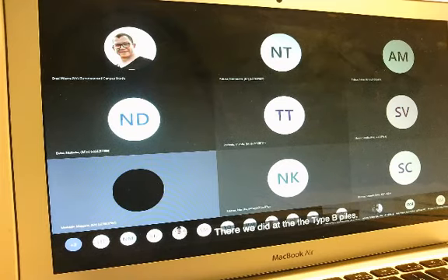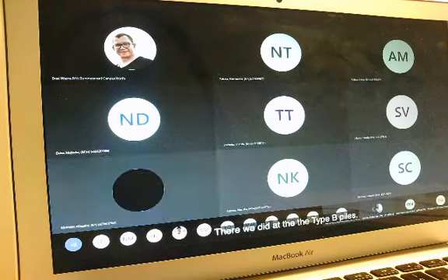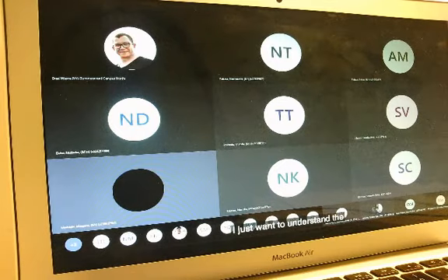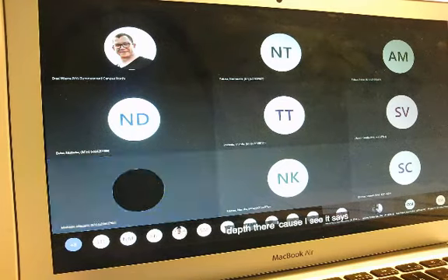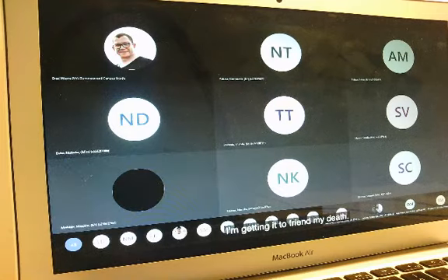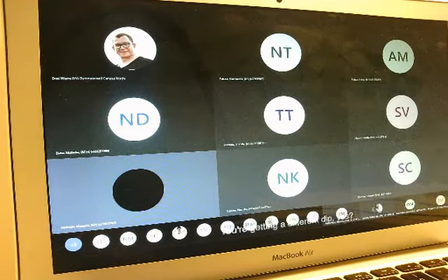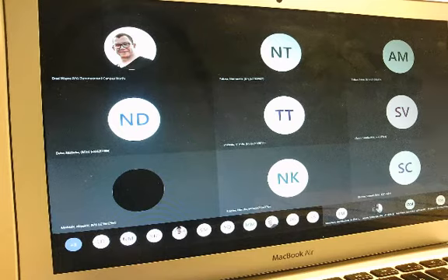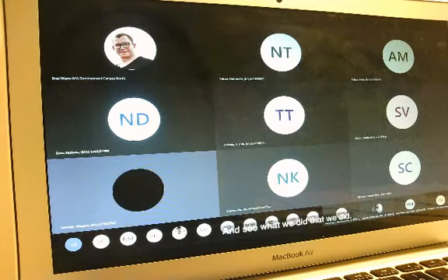You see where we excavate for the pile caps, there's the part where we deduct the protrusions for the actual piles, where we deduct the type B piles. I just want to understand the depth there because I'm getting a different depth. You're getting a different depth? Yes.